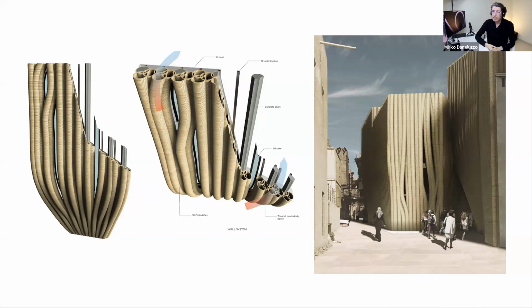And because the lower levels are detached from the ground, they are creating some wind flows, channeled from the top and the bottom. So basically, you have the possibility to create these air chambers inside that help to isolate the building from the high temperatures that you can reach during the summertime in this region.